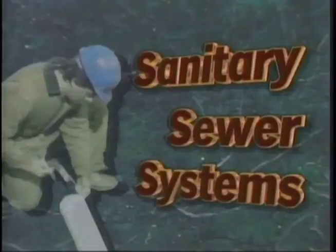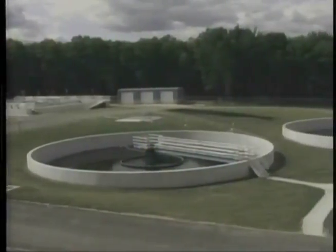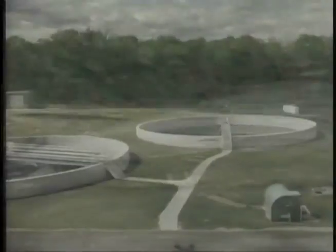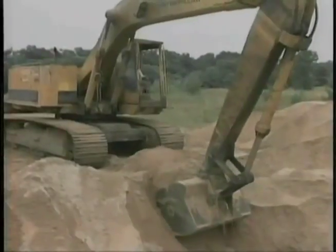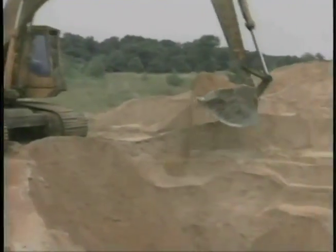A mainline sanitary sewer routes wastewater from a community to a treatment facility to be processed before its release back into the environment. Sanitary sewer pipes are commonly installed with a small amount of gradient. If the slope is too great, the liquids tend to separate from the solids and create blockages. Direction changes for sewer pipes can also cause blockages.